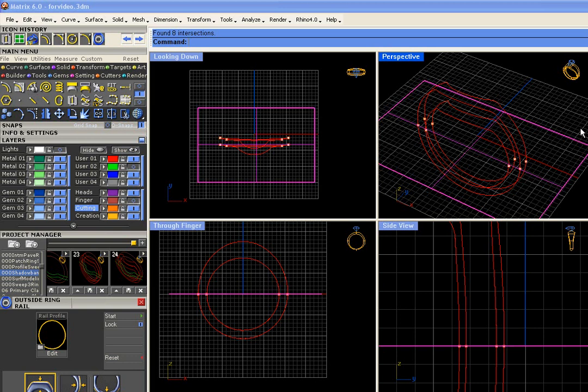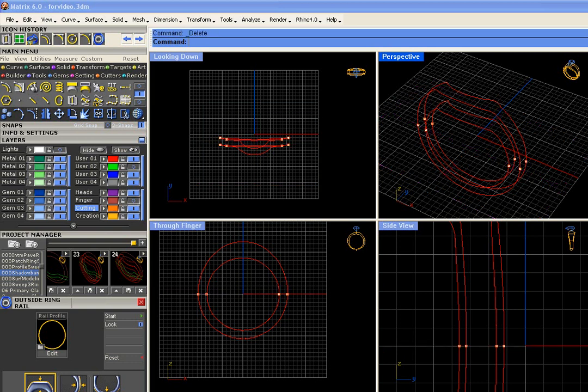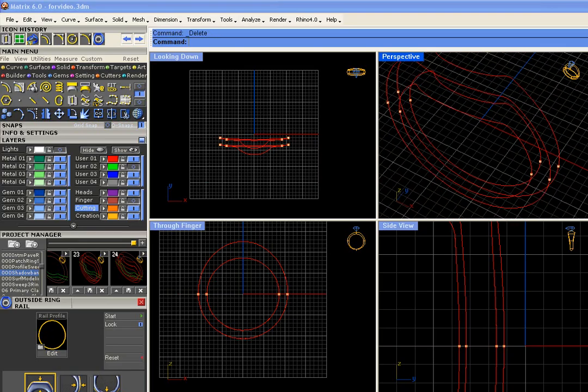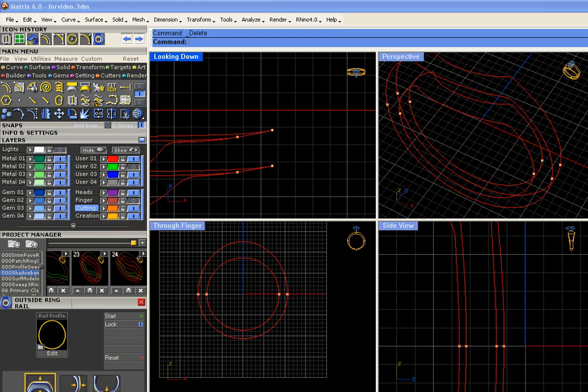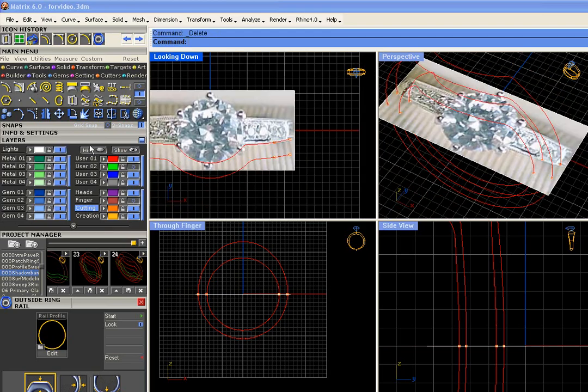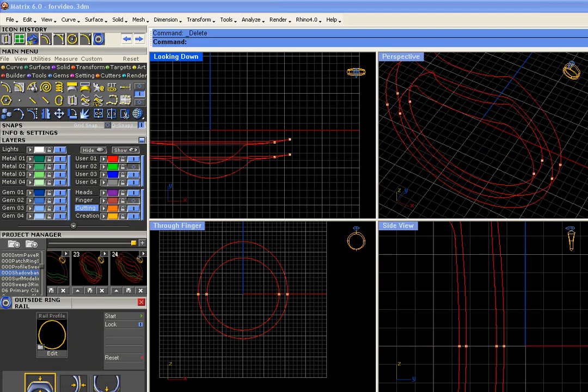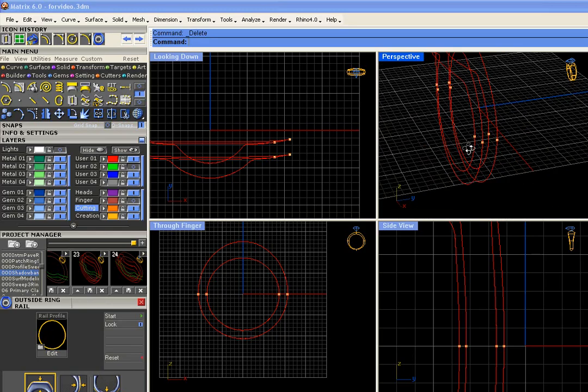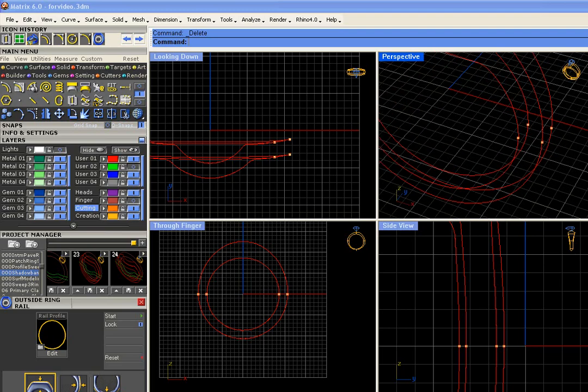The reason we did this is because these curves, this might not be their quad anymore. We really don't have a snap point right here to which to draw these profiles. We want to make sure the profiles match the rails exactly so that they're at this unique little angle where they have to nestle up next to your engagement ring. Okay, so that's the best tool I know. Place that plane, select the new rails, and run intersection to place points right here so you have something to snap to when you're drawing these profiles.